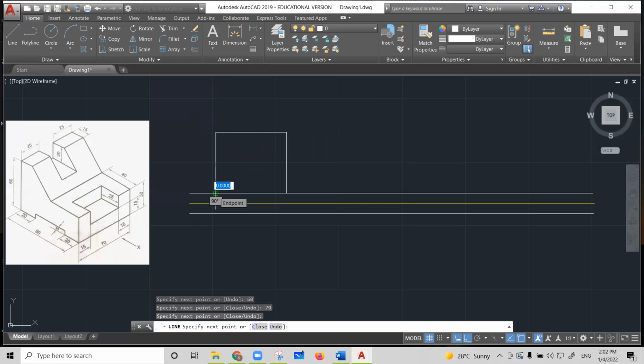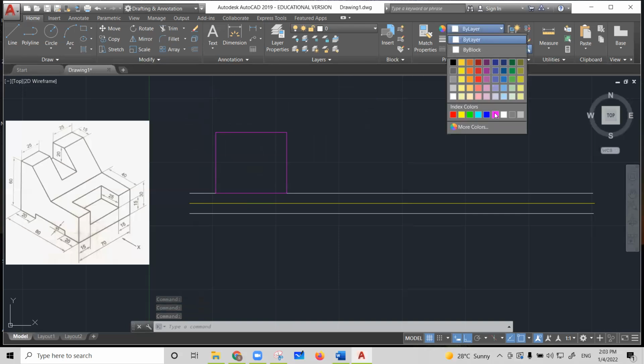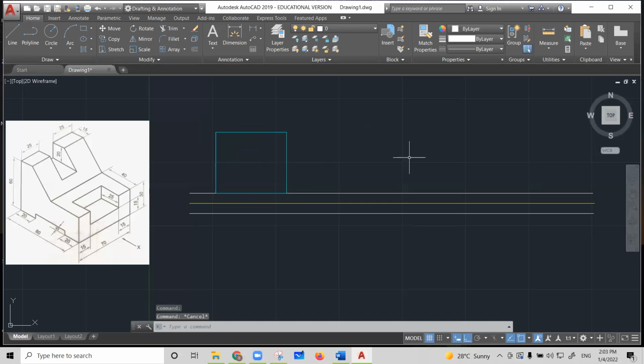In this AutoCAD I will make it visible to you clearly. So I will convert these boundaries into another color, so you can easily recognize the difference between that and those drawings in terms of boundary, right? So this is nothing but the boundary for your front view. Length is 70, height is 60. Then I will start taking the projection from here. Instead of taking the projection, what I can do is go to this point, and then take the projections in line with that.